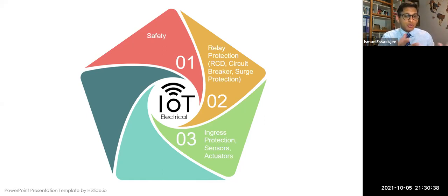Sensors and actuators, we introduced sensors and actuators. Number 4, have a look at electromagnetic interference, because it can affect the integrity of the data and the way your system is going to operate. It can malfunction as well. So be careful about this selection, about where the cables are going to go, where you're installing your device and so on. And then number 5, we quickly went through what we call the battery system, and you have a link to help you do your sizing as well.